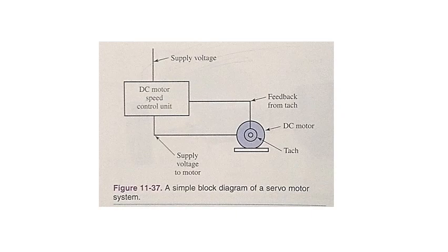Another type of feedback system is the digital encoder. The digital encoder sends pulses back to the control unit rather than varying the voltage. An electronic counter counts the pulses generated by the encoder. By counting the pulses, the system can accurately determine the number of revolutions completed by the motor and the position of the device the motor is driving. The device could be an assembly line conveyor belt or even a DC motor driven robotic arm.